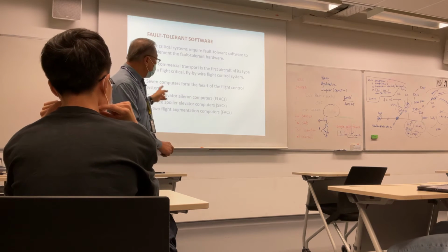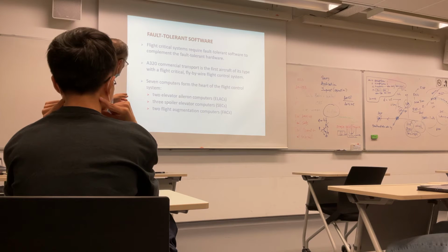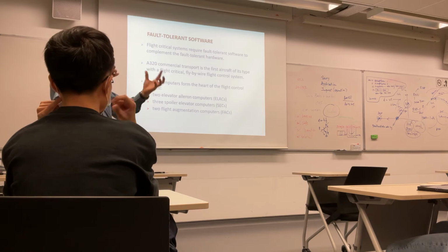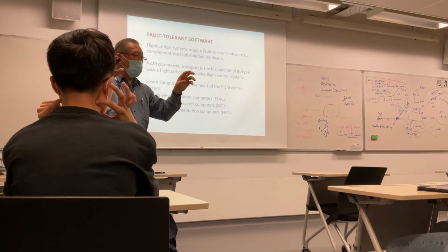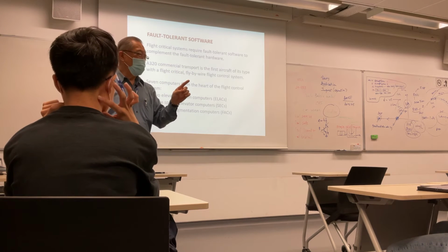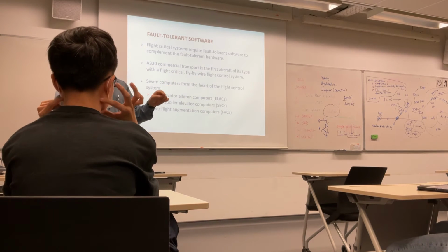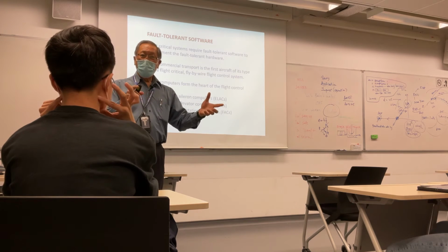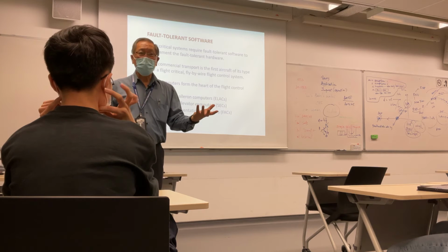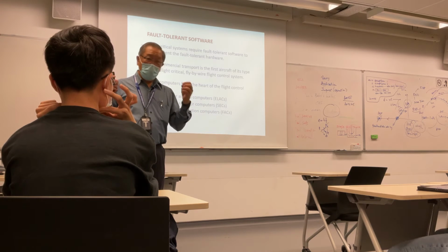So in the aircraft system, you have this elevator and this spoiler, all this hardware, 5 channels of autopilot. The 2 channels cannot use the same chip. Because if Intel programs an error there, the same programmer, it affects both channels. Then your effort to have duplication is wrong. So we take care of all these things.